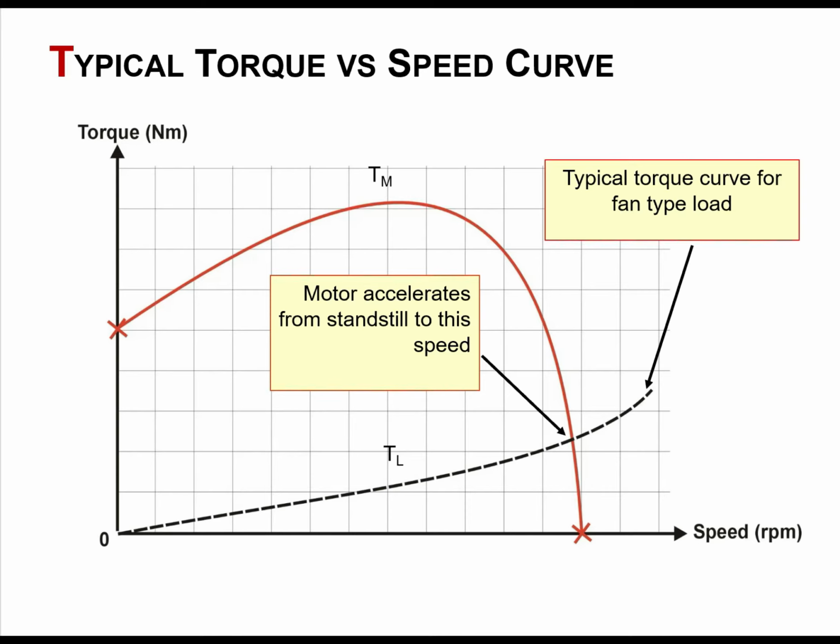To understand this, it is important to know that when a motor starts to rotate from rest, a locked rotor torque or breakaway torque is developed. It is usually larger than the full load torque. And then as the motor starts up, a pull-up torque is developed as the motor speeds up. The torque continues to increase until it reaches the breakdown torque.